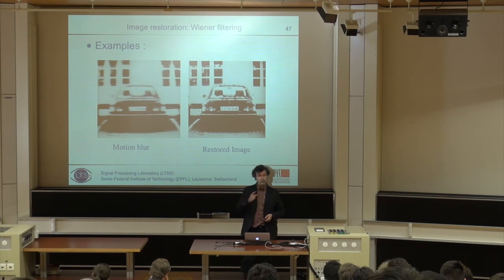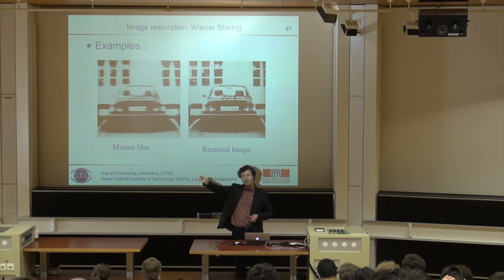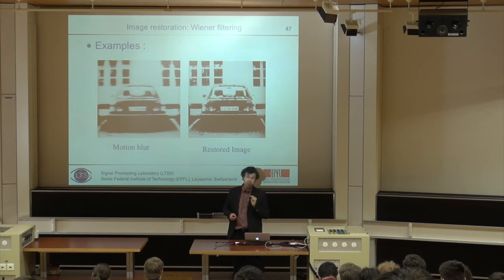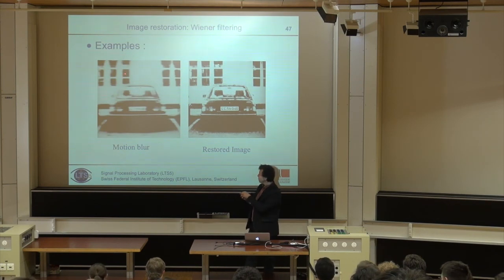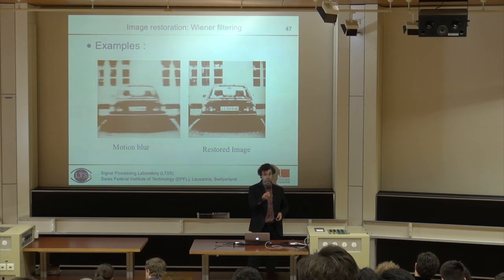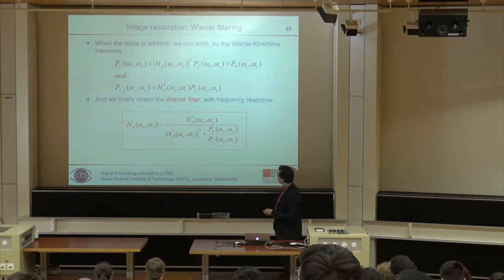It's just the result of the convolution of a step. And if you take a step function and you differentiate it, you get an impulse. So if you get the response to a step and you differentiate it, you get the response to a pulse. And the response to a pulse is by definition the impulse response. So from the response to an edge, you really see the impulse response. To be precise, the integral of the response.